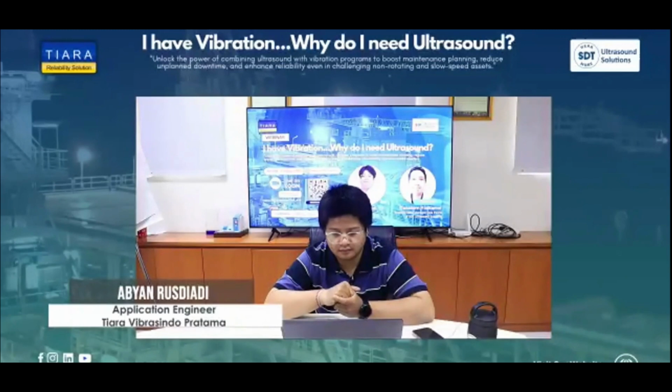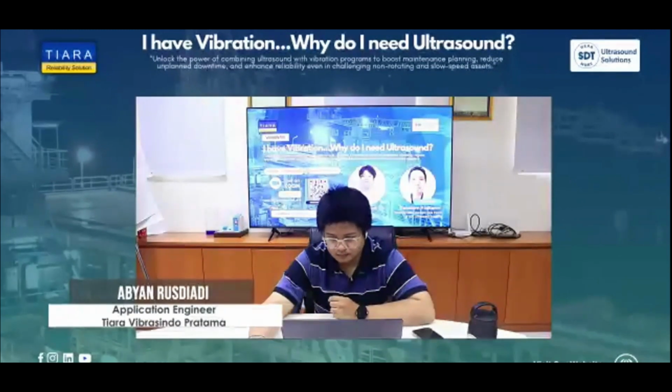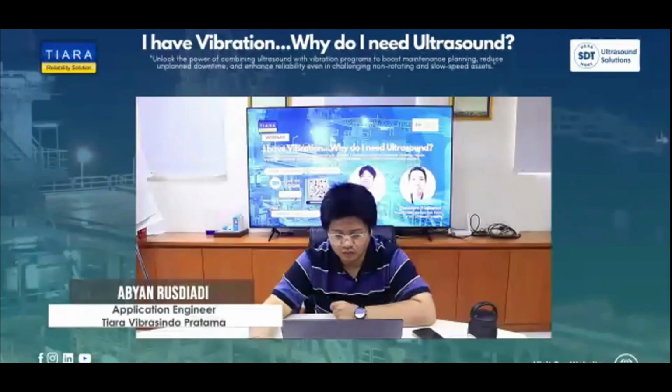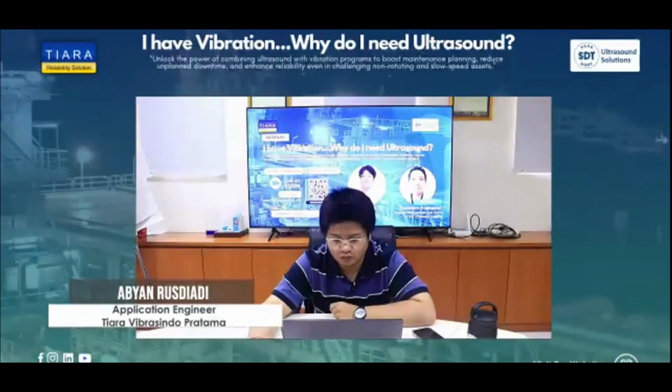axis. Because normally for the airborne sensor, we set the default to allow 25 kilohertz to 60 kilohertz. If you think this frequency range is wide, you can set it narrower, like 30 to 40, or 40 to 50, or 50 to 60, depending on the asset that you want to measure.